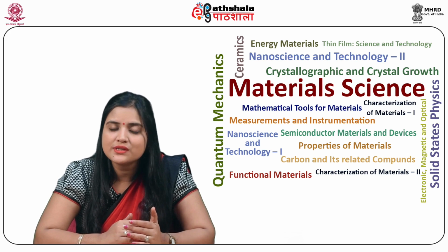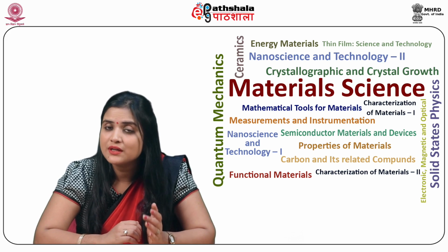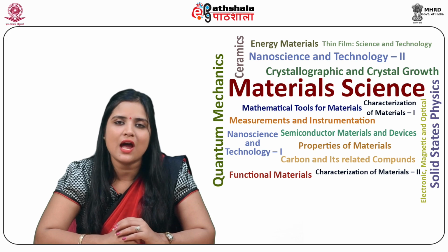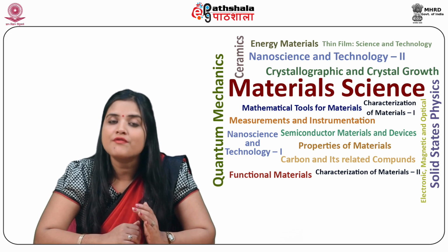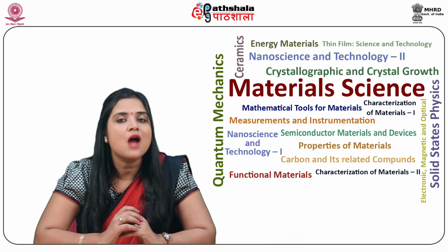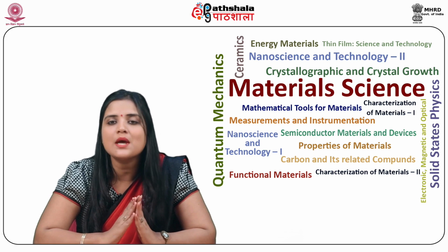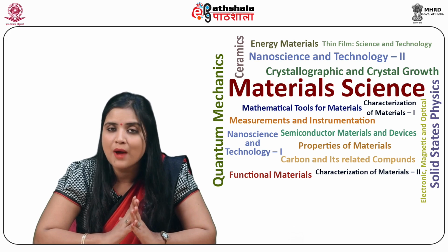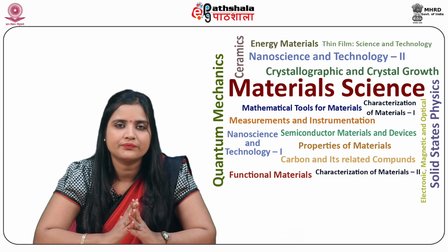Also, the load is isolated from the frequency determining network and thus it will not affect the characteristics of the filter. The third advantage of active filters is its low cost. Active filters are more economical than passive filters because of the easy availability of cost-effective op-amps in comparison to inductors which are costly.